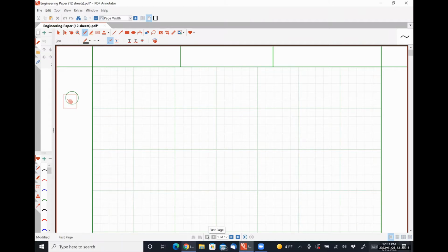Okay. So the first thing that we're going to talk about today then is the self-biasing network for NMOS transistors. And we're going to start without channel length modulation. So the self-biasing network looks like this.